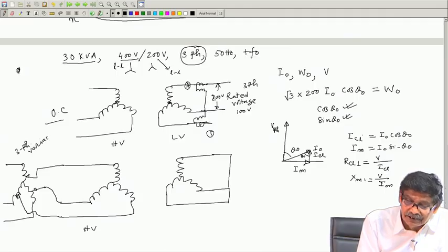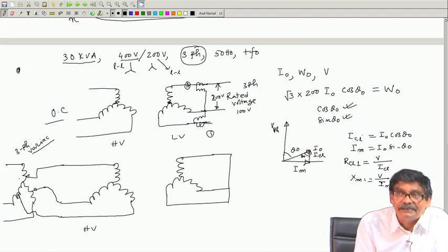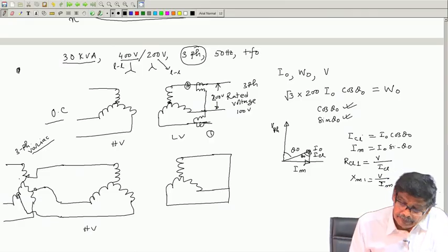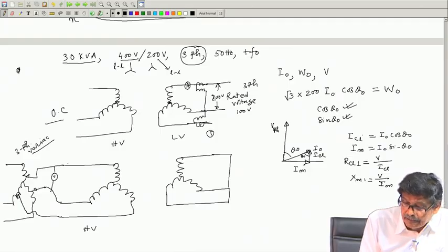because you must be knowing the difference between a variac and an auto transformer. Auto transformer means in this winding you are using different sections of wires, you get an advantage. Anyway, you measure the voltmeter reading here VSC, you record the current, you connect 2 wattmeters.